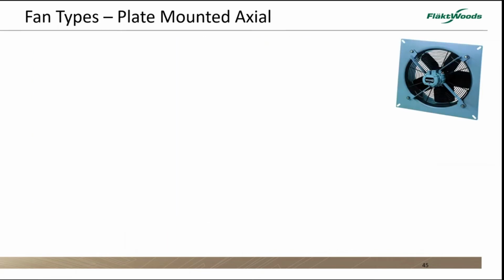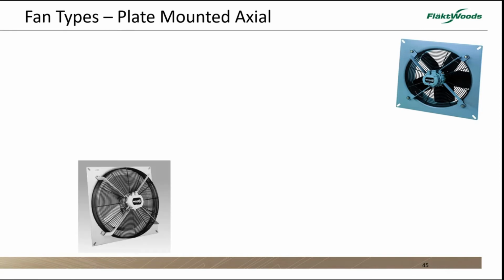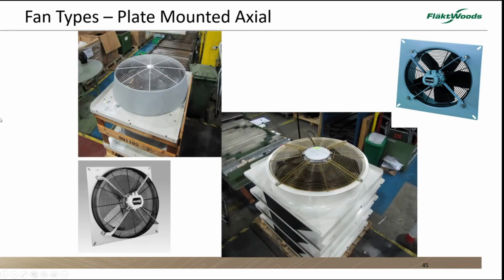Right, plate mounted fans. People have been used to seeing these in the walls of barns and places like that, just generally used for that, but also for the heat transfer market. We have a plate mounted fan where we've got our fan. It's a type A installation, no duct inlet or outlet. And the fans are made so you design specifically for the efficiency of that arrangement to try and make it the best that you can.